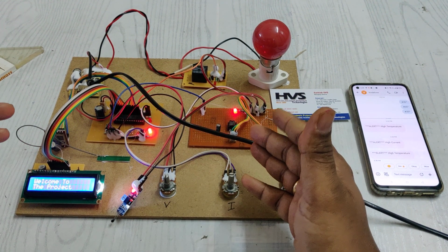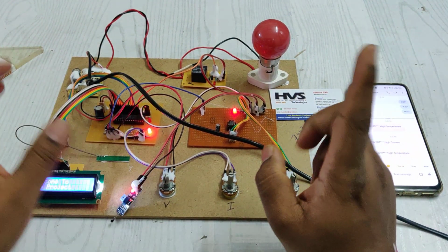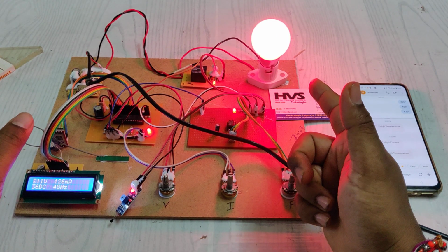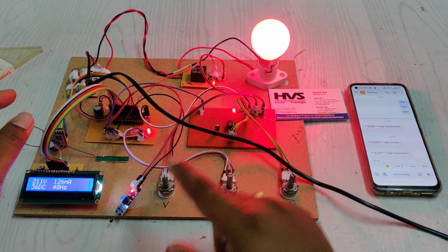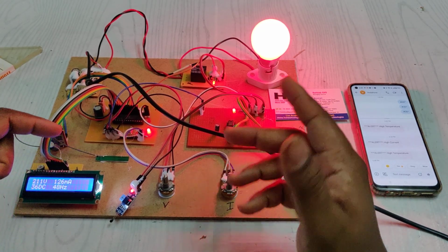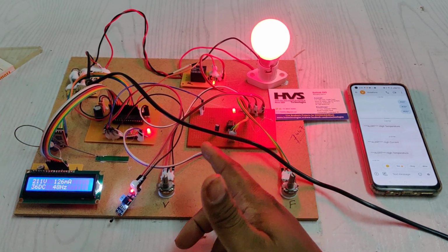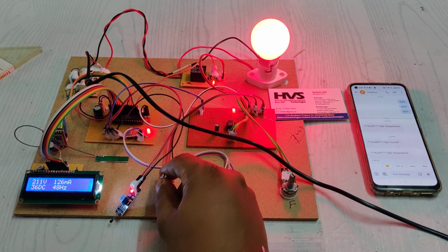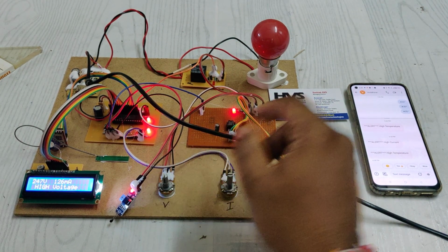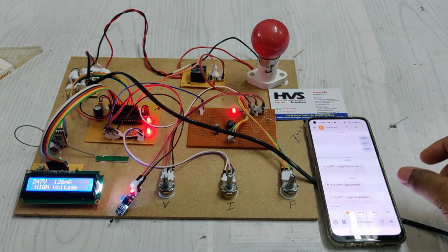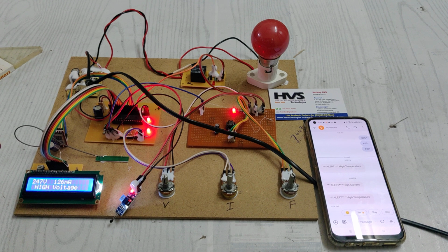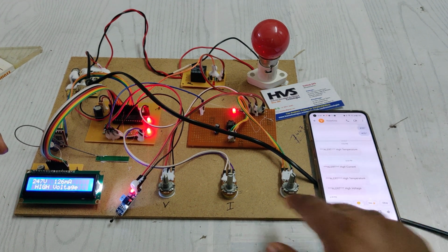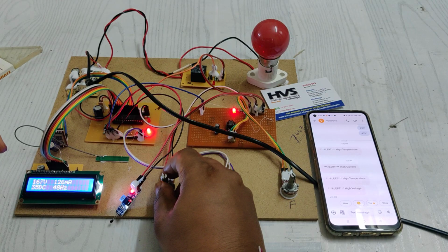Whenever an abnormality is detected, the system will send message alerts and the circuit breaker will be off. Then when it is normal again, it won't control the circuit breaker through auto reset. We need to do a manual reset to make the circuit breaker controlled again. Whenever the voltage increases above 245, it is high voltage, and we receive the message alerts on the mobile phone. So we got the high voltage alert, and when it goes below, we get the low voltage alert.